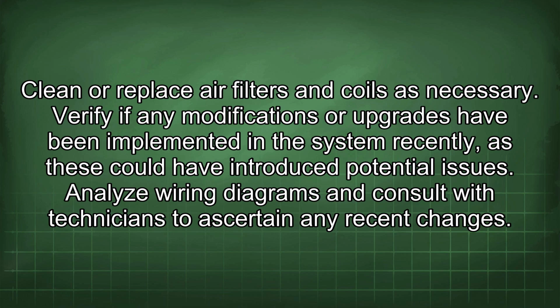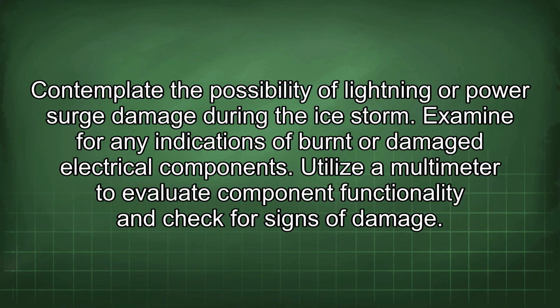Verify if any modifications or upgrades have been implemented in the system recently, as these could have introduced potential issues. Analyze wiring diagrams and consult with technicians to ascertain any recent changes. Contemplate the possibility of lightning or power surge damage during the ice storm. Examine for any indications of burnt or damaged electrical components. Utilize a multimeter to evaluate component functionality and check for signs of damage.